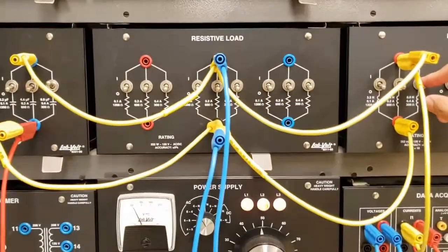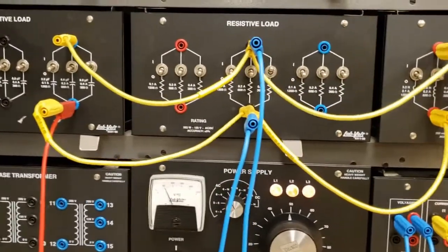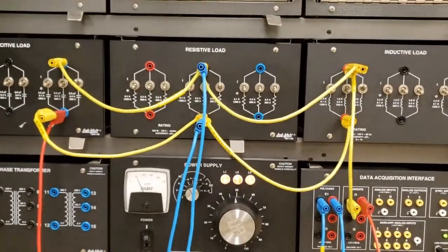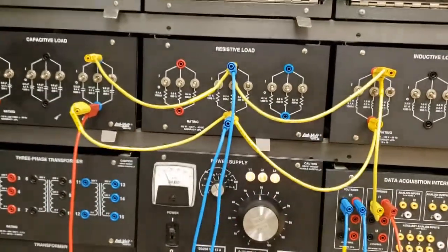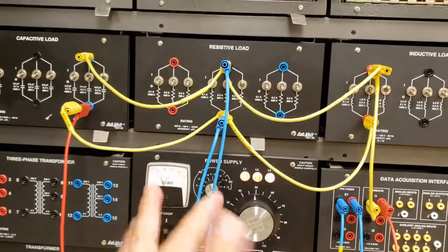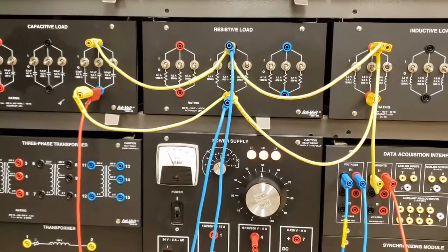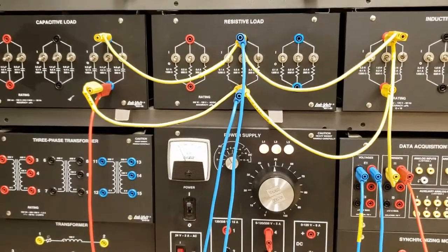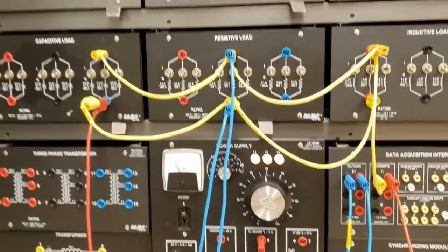The last part of part A is where you have all the loads connected at once. So the resistive load and the inductive load I'll put in. Now what should happen is the resistive load will remain as is, but the inductive and capacitive loads have equal and opposite admittances, and they are in parallel. So their admittances summed together will add to zero admittance, which means no current will actually run through them from the power supply. So there'll be an open circuit.